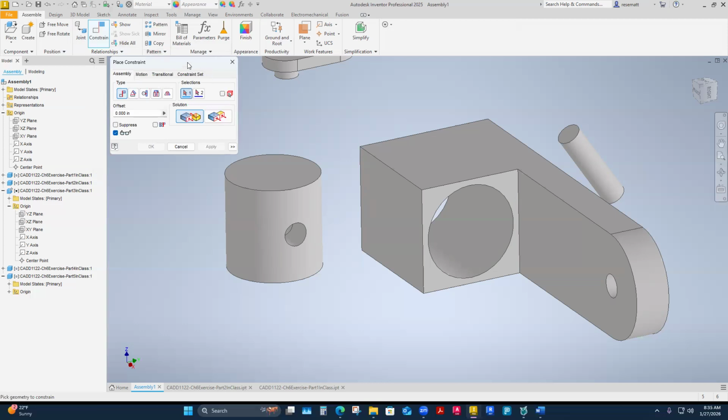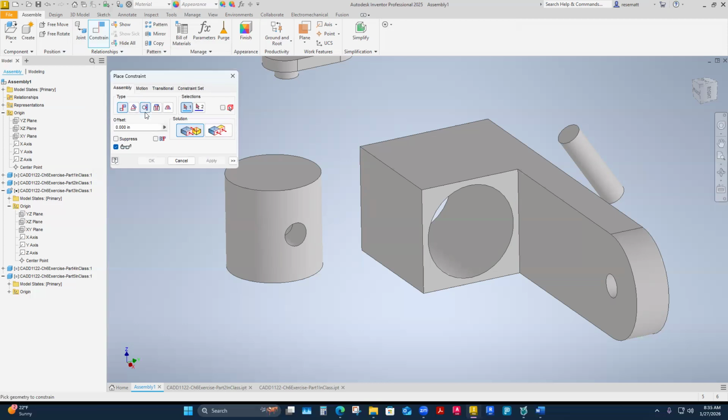This little dialog box shows up, which is a small dialog box with a lot of power. So really, I have what, like four different tabs here. The assembly tab is the one I use the most. I would say I use motion less. I feel like an engineer when I'm looking at some of these others, but let's see here. Just a simple assembly tab here. Then the type of assembly I have is what? A mate. What is this? An angle one, a tangent, an insert, and a mirror or symmetrical, how I would constrain this.